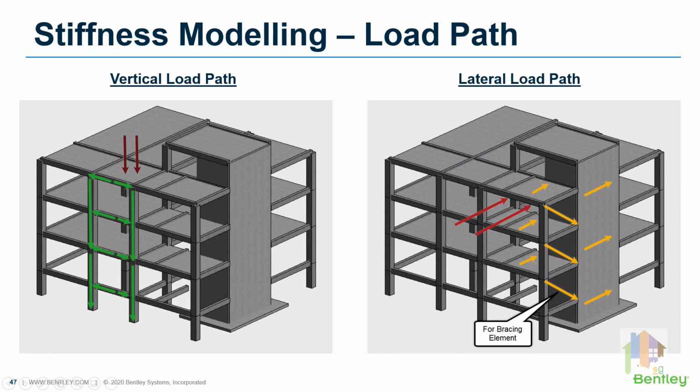We know for any normal beam column slab structure, gravity load transfers from the slab to beam, then to column, and finally to the foundation. For lateral load like seismic load, the transfer path is different from this. Here, load is transferred through the lateral load resisting frame from slab to shear wall or bracing and finally to the foundation. So both diaphragm modeling and placement of shear wall and bracing is very important for any seismic efficient structure.